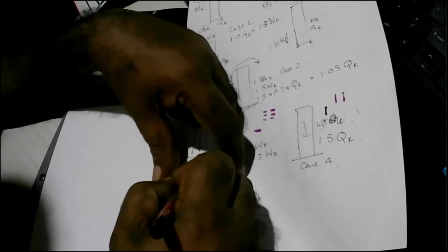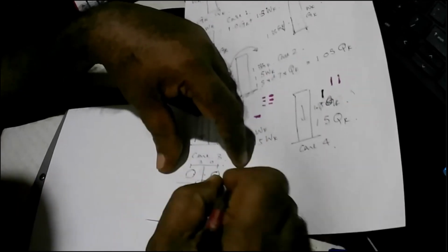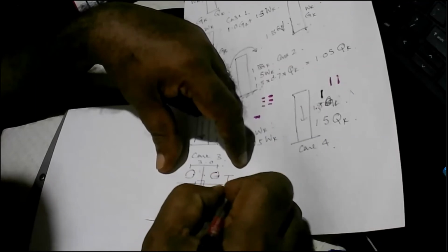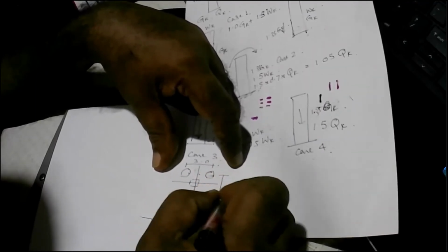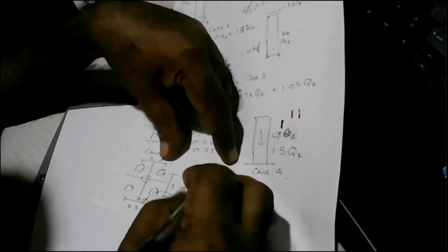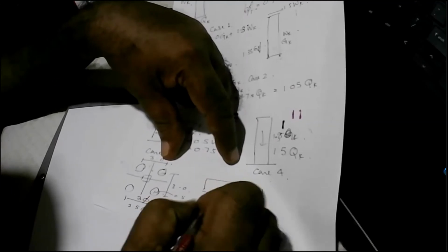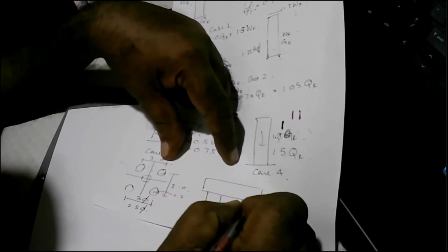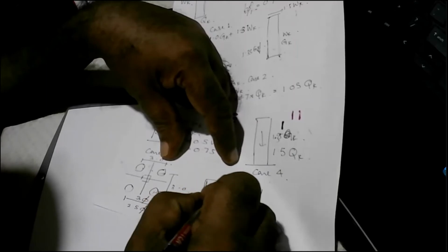So if you are going with 3 times diameters, then the distance between two centers will be 3 meters and 3 meters. And the pile radius is 0.5 meters here. And the pile cap will need a minimum of 150 millimeters to bend the reinforcement and anchor it.